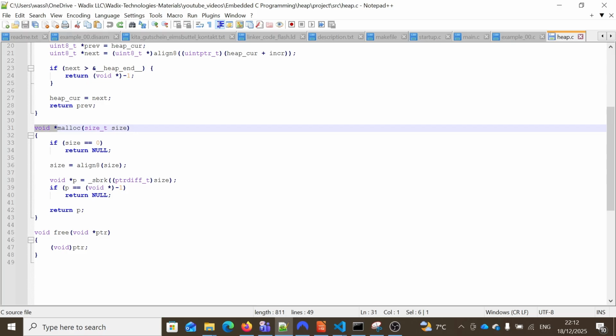For example, if we are going to deploy this function within an ARM Cortex-M0 or M1, and we allow providing an unaligned pointer, then we are risking performing an unaligned access to a memory region. And the M0 and M1 do not support unaligned access. Hence, we'll end up having a hard fault.